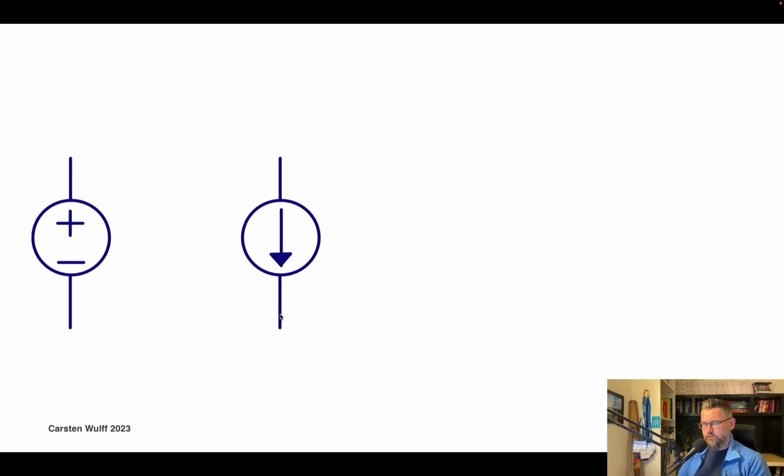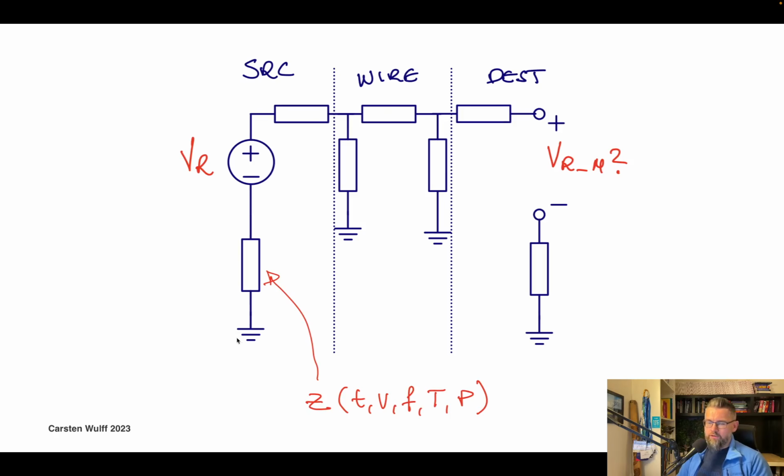So what do we do then on chip? Well, we have to think about this concept of voltage, because all through the studies we often talk about the voltage in a node. We say, okay, this node is at 1 volt, this supply is at 1.8 volt. But when we go back to the equations and look at what we mean by voltage, it is always referred between 2 points. There is no such thing as the voltage in a node. The only reason we have that is because we've come to an agreement that we refer all voltages to this magic place called ground.